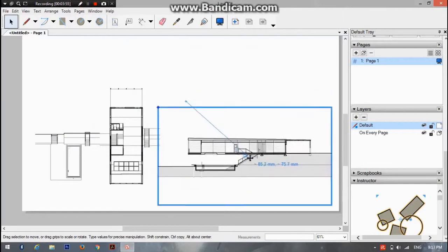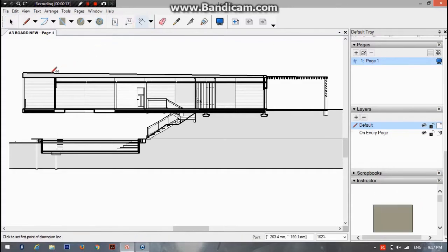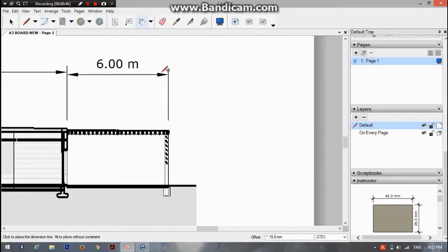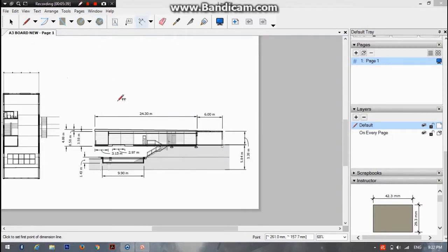A section is then placed using the previous method. As this particular section is used to show the dimensions of the drawing, press on the scale icon to turn the mode on. Now, click two edges to obtain the interval dimension. Repeat the same way for the next measurements.